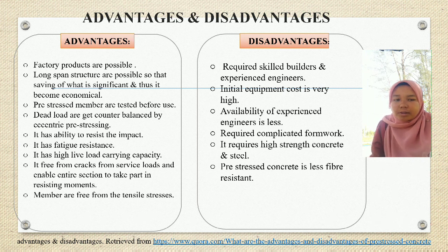For the disadvantages of prestressed concrete, there are six. First, it requires skilled builders and experienced engineers. Second, initial equipment cost is very high. Third, availability of experienced engineers is less. Fourth, it requires complicated formwork. Fifth, it requires high-strength concrete and steel. And the last, prestressed concrete has less fire resistance.